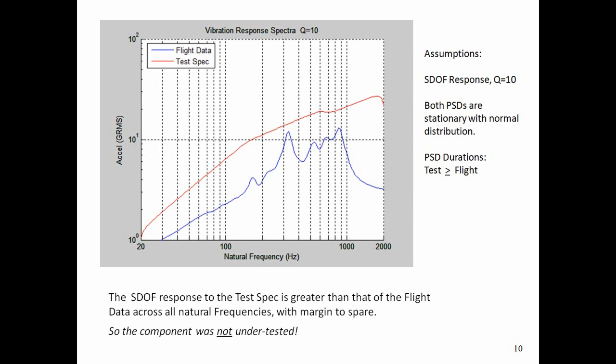And in the case of an actual flight unit box, we would start to worry about accumulated fatigue cycles if we're putting it through an additional round of base input PSD testing. So that's one of the things we get called upon as engineers, to show qualification by similarity or qualification by analysis, whatever you want to call it, or otherwise just to prove that retesting is not necessary.